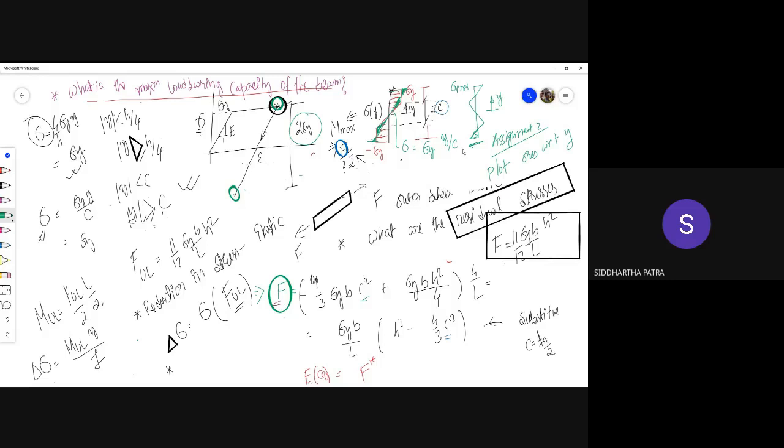Because the loading part was elastoplastic and the unloading part was elastic, there would be several pockets in the cross section where there would be positive and negative stress states locked within the material. Simply locked in the material. There is no one who can take those stresses out. I mean, yes, there are processes to do that, but not just mechanical processes. You'll have to heat treat that and something else.